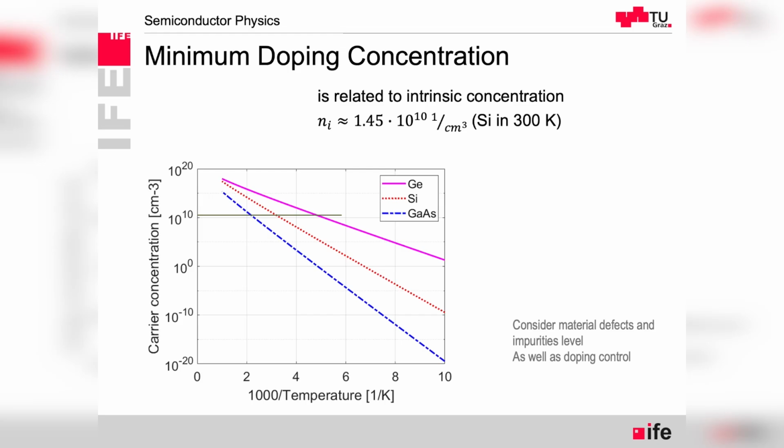And we can see also from this plot that the same dopant level concentrations would not work for germanium or for gallium arsenide, because we just need completely different levels. Our reference point here is, let's say, our target operating temperature is room temperature, so that's our reference for how we want to dope the semiconductor.